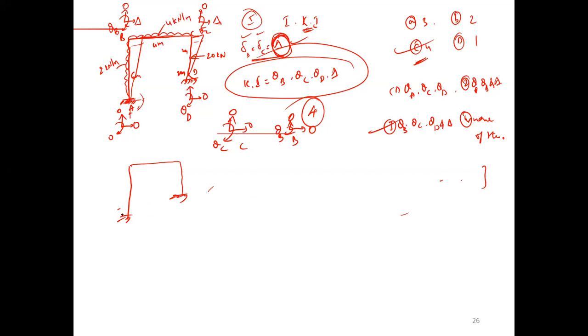If it is a rectangular frame, you are assuming like this sway. First condition. This is positive sway. Then it must deflect like this. Definitely it will come to here because this is delta. This length is same, this length is same.